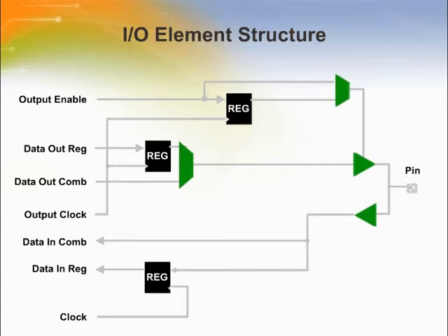The IOEs are located in I/O blocks around the periphery of the Cyclone II device. There are up to 5 IOEs per row I/O block, and up to 4 IOEs per column I/O block. The row I/O blocks drive row, column, or direct link interconnects. The column I/O blocks drive column interconnects.